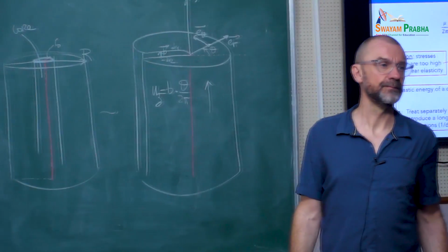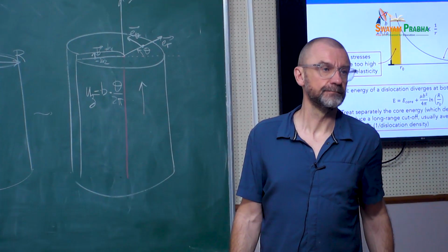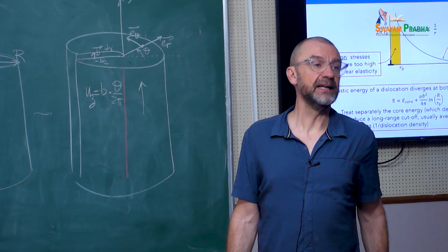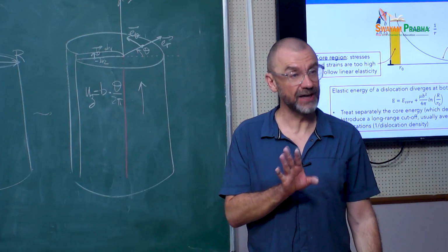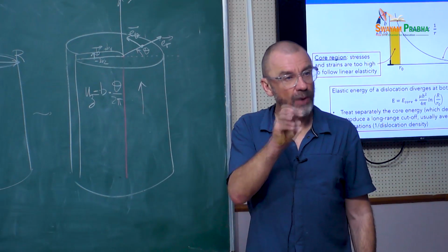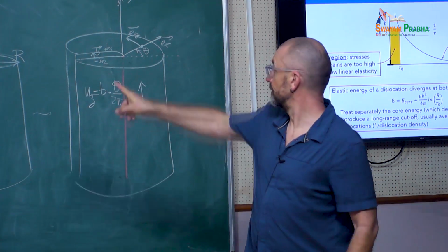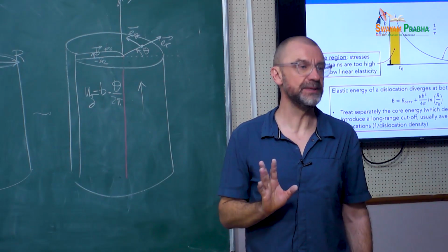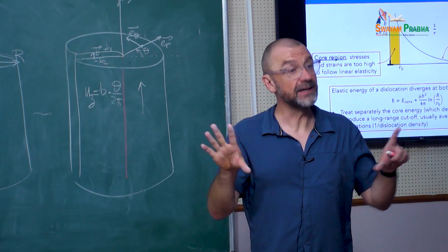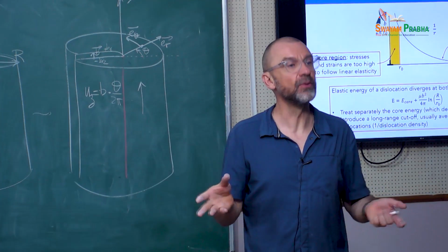Yes. But we would like to keep it around a few atoms? In practice, it depends on the dislocation. If I have a compact core, like I've drawn here, usually 1b is enough. But there are some extended cores where you have to take more than just 1b.